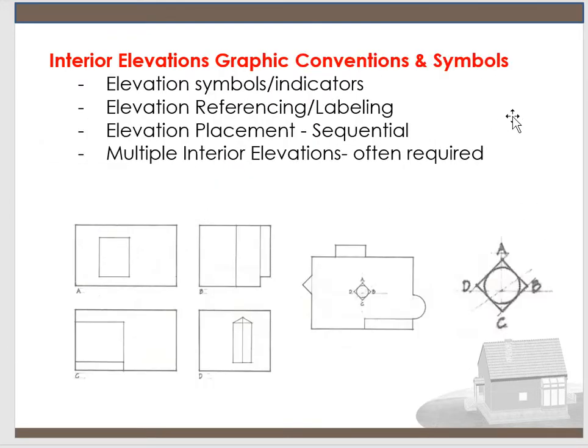So elevations, some of their graphic symbols. As I alluded to, this is one of the most important graphic symbols that will be found on a plan view, the floor plan. This is called an elevation symbol. And this is a reference symbol. This is referencing which view we are looking at.